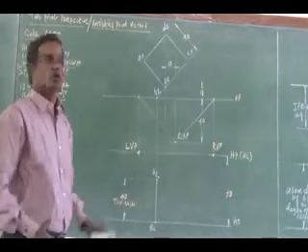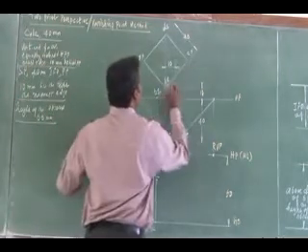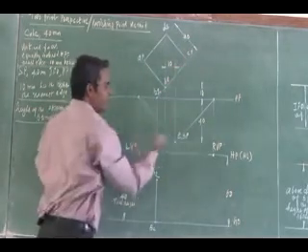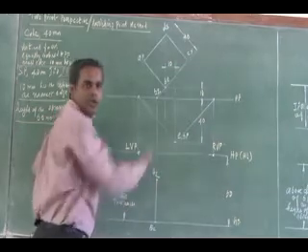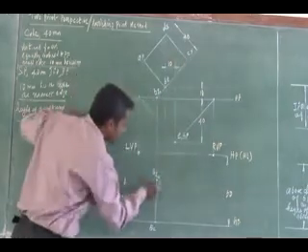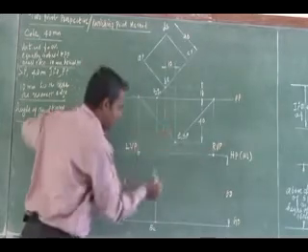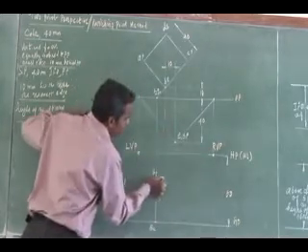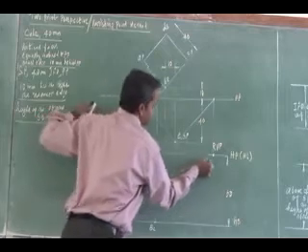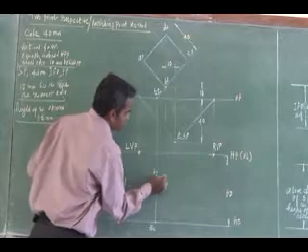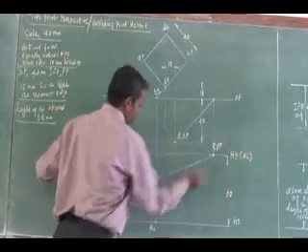So now to get the perspective location of the BQ edge and CR edge. In which direction have I extended? To the right vanishing point I have extended, right? So this B2Q2, I am going to join it to the right vanishing point with two vanishing lines. This is a vanishing line corresponding to Q2.